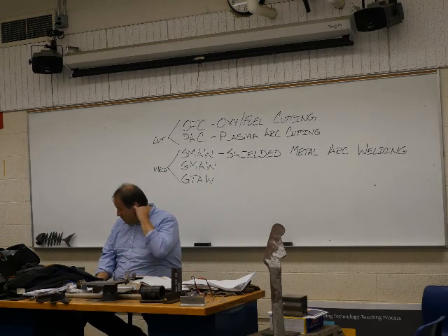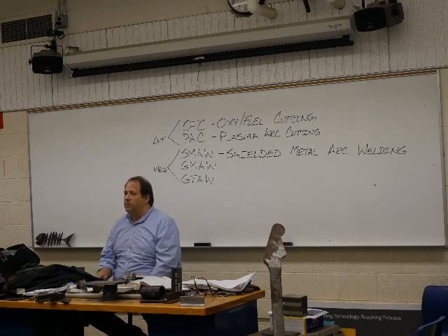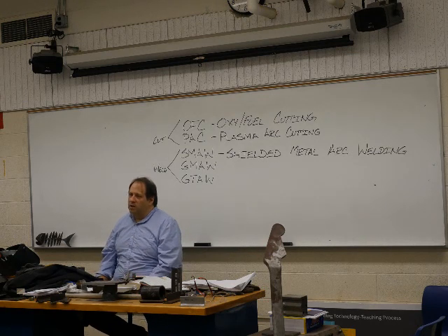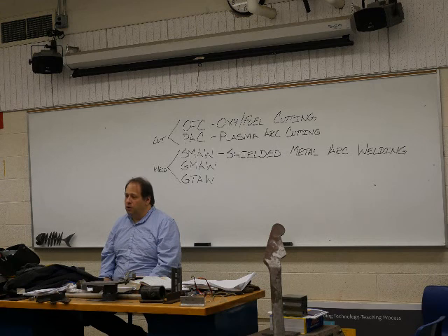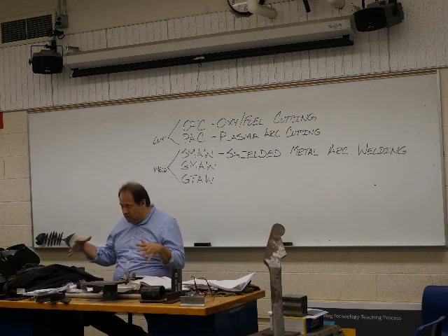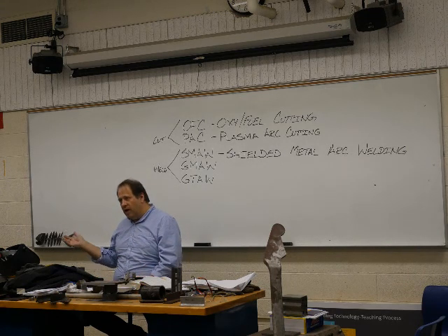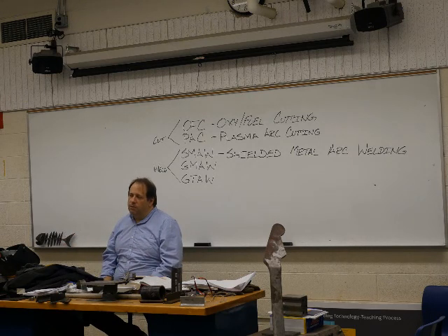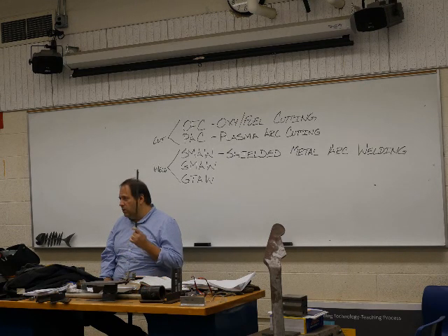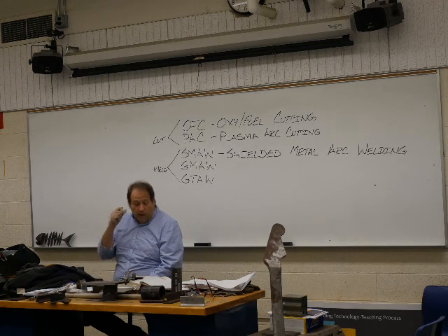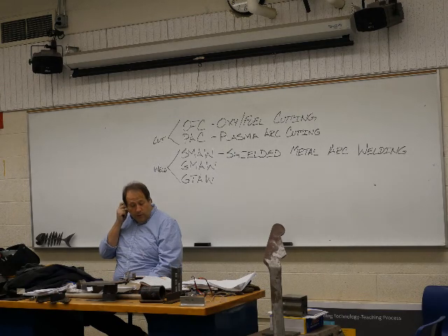This process has been around for a while, but yet it's still very viable today. It's still one of the best processes for using outside, underwater, in bad conditions, in places where it's hard to get a machine sitting there near you, but you can run a long cable. So this is really still a pretty big process in the industry. Probably 65–70%, I would say, is still stick welding. So even though it's pretty old school, it still gets done a lot. So it's good to know this one.